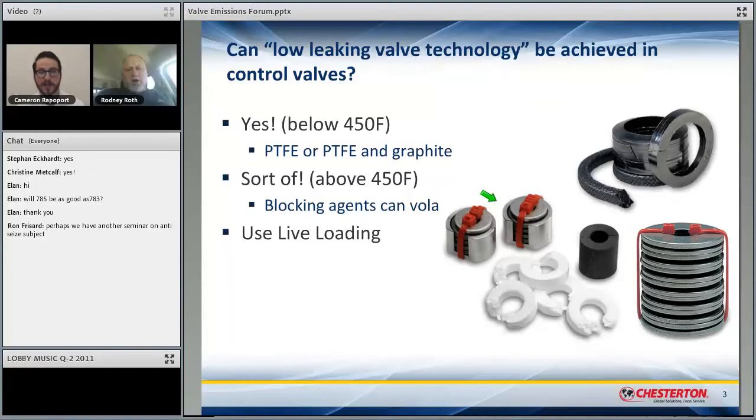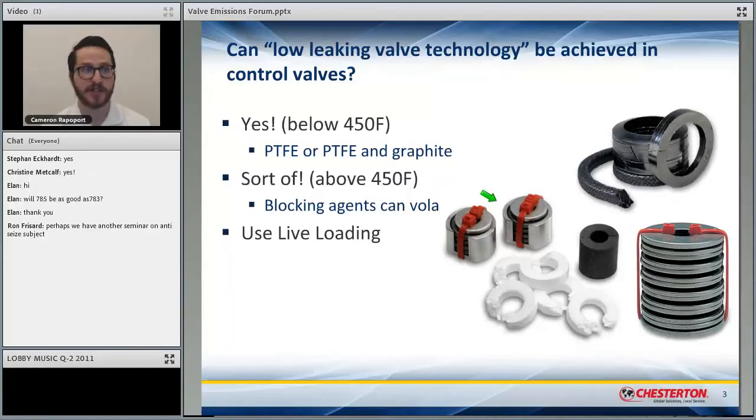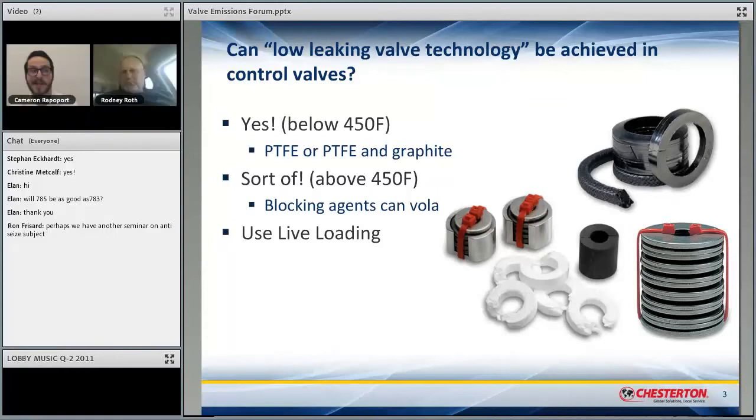In certain applications where you think you might lose that bolt stretch, and especially in control valves, you can use these springs to actually load it instead of the bolt, because the bolt doesn't have a lot of room. If it grows or shrinks or loosens up a little bit, you're going to lose a lot more stretch than you would if it does so in one of these big spring stacks.